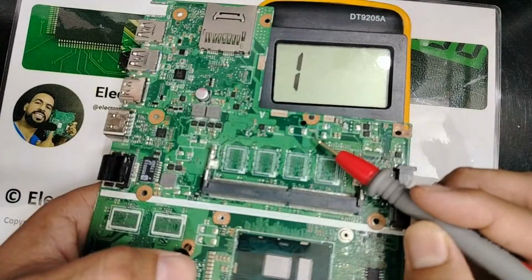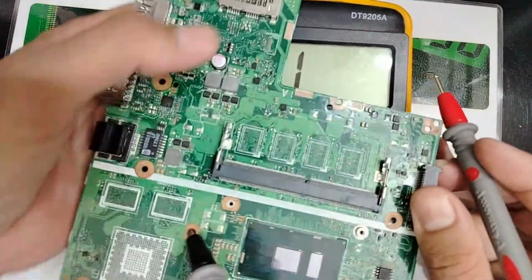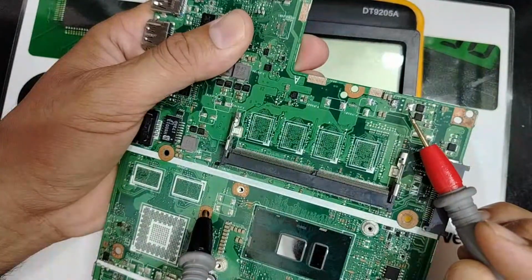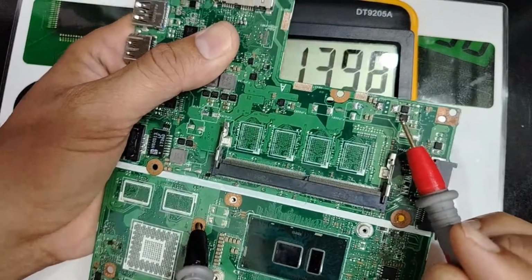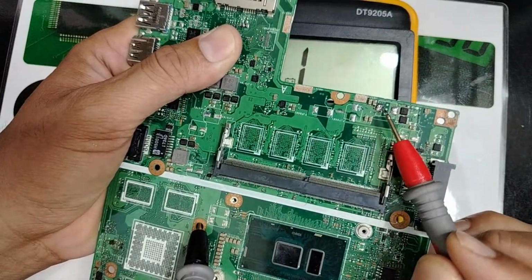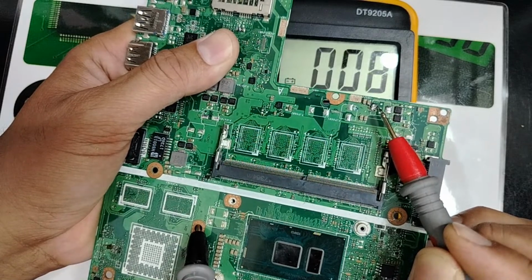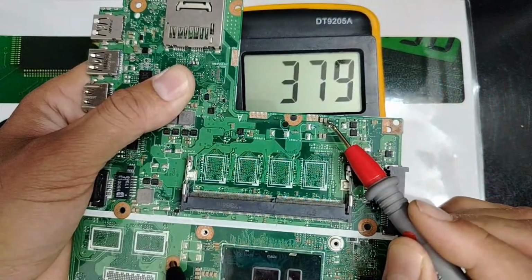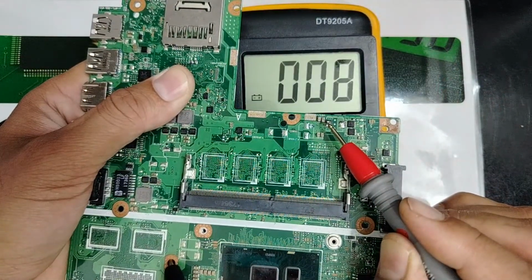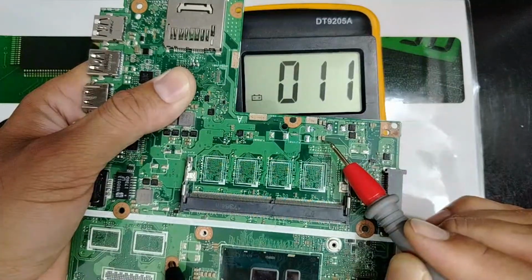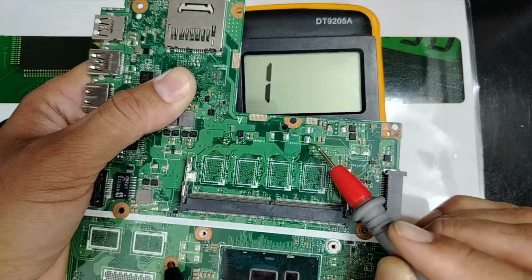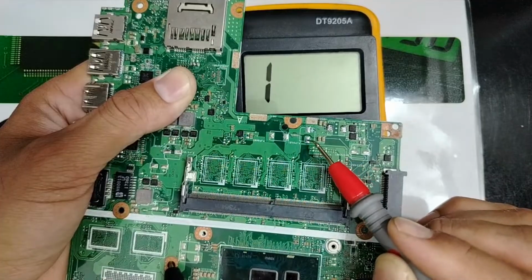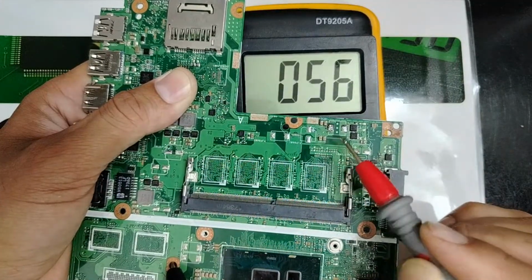After removing the pad, guys, I didn't like this auto zooming. Okay, my friends, after removing the inductor, the short is gone here. After removing the pad, we get 9 here. Do you see? We get 9 on the multimeter. Also 9 here. But here, normal, we get 0. Why? Because this side is connected to the ground. This is the ground. Here we have an electrolytic capacitor. Here we have plus ground. Here, normal 0. But here we get 9.